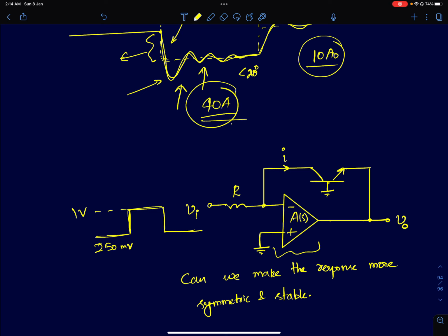So from these audio microphones, which would go through amplifiers. My analog professor would just say that the first trick he would do is just reduce the loop gain, reduce the gain of this amplifier. And suddenly, once he reduces the gain, you'd stop hearing this ringing noise. So reducing the gain is one quick way of fixing this problem.